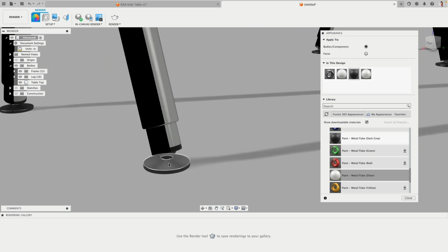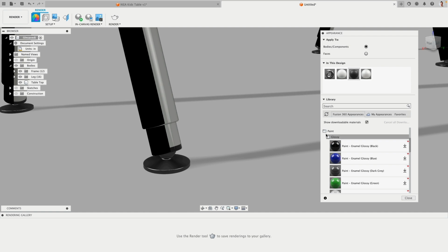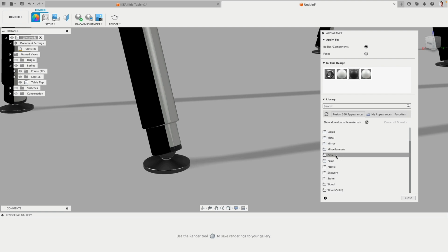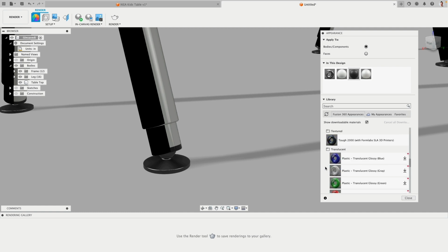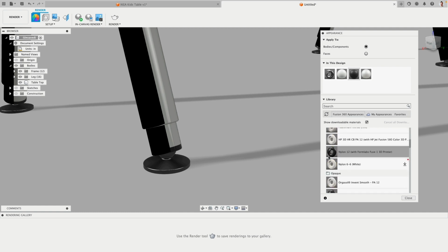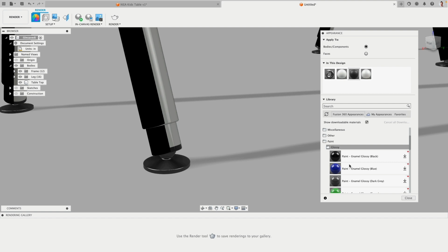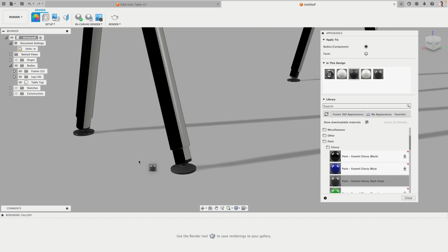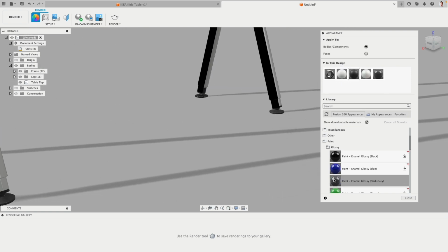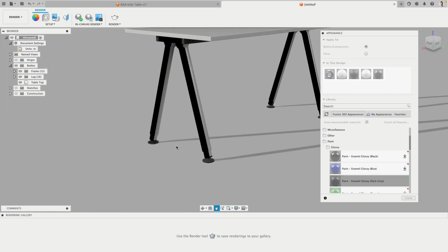Okay, I will turn the rendering off because based on how strong your computer is, that runs faster or slower. This, for example, was matte on top and then glossy at the bottom. So in this case, I could go with the plastics, but they can run slower because they are calculated correctly. I will simply go to paint and glossy. So I do have, for example, this dark gray. I will not use black on purpose because black and white can in renderings turn out very, very dark.